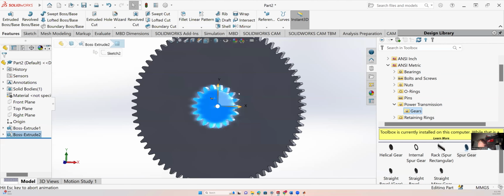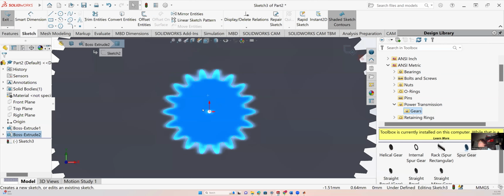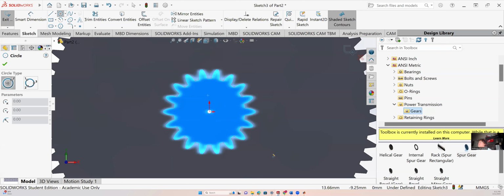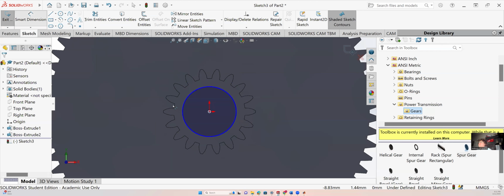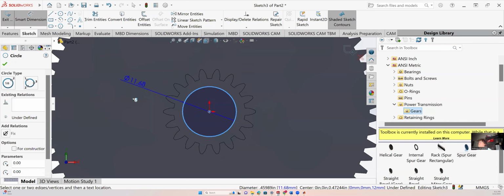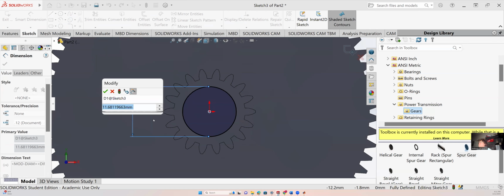So let's make our 2 diameters on this surface. I'm going to make our larger diameter first. If you remember from the beginning of this video, the nominal diameter of our bearings is 10 millimeters, but we have our delta, which is the amount of interference that we want.